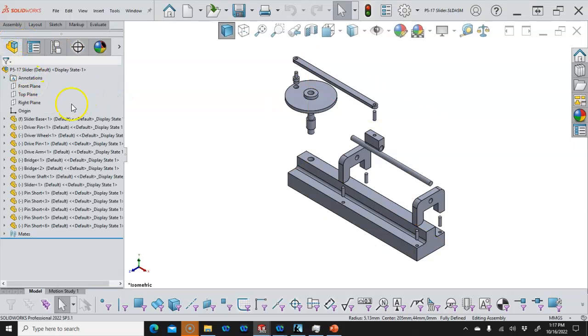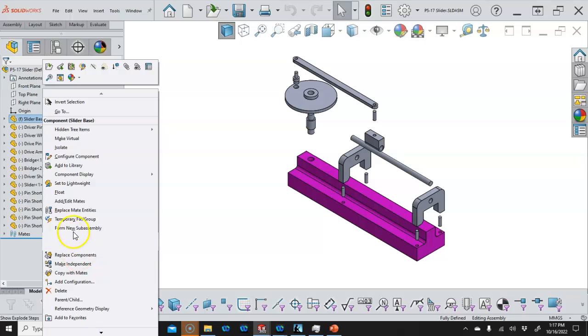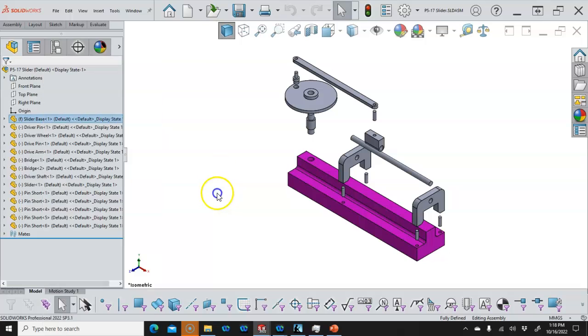between my tabs. So if I wanted to leave this slider, we would make a configuration. If we want to replace it, then I have to look down through here and find the replace. But this is kind of a permanent. Replacing the components means that we're removing the revision 1 and we're putting in its place revision 2.